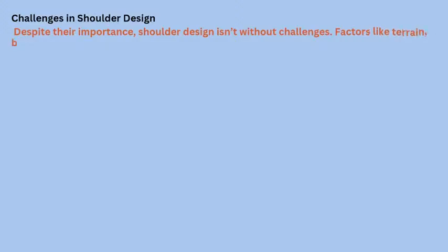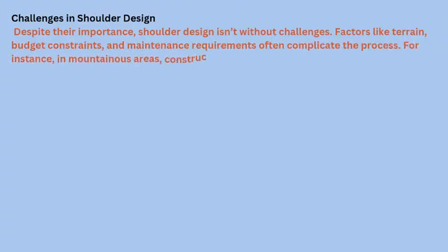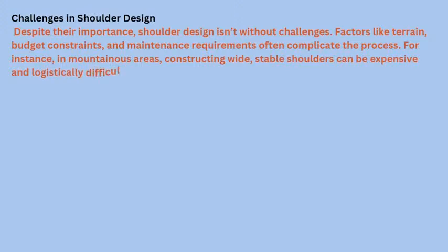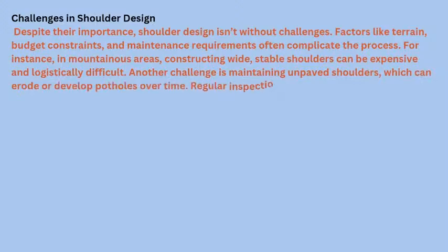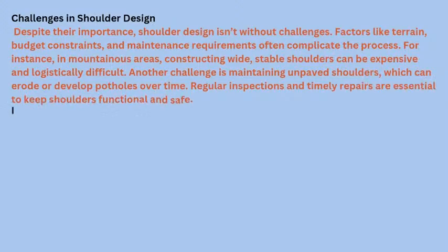Challenges in shoulder design. Despite their importance, shoulder design isn't without challenges. Factors like terrain, budget constraints, and maintenance requirements often complicate the process. For instance, in mountainous areas, constructing wide, stable shoulders can be expensive and logistically difficult. Another challenge is maintaining unpaved shoulders, which can erode or develop potholes over time. Regular inspections and timely repairs are essential to keep shoulders functional and safe.